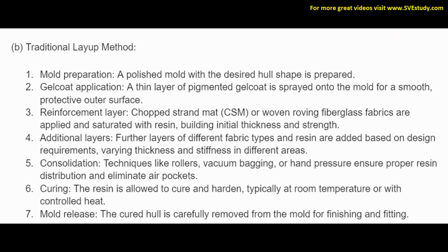B. Traditional layup method. 1. Mould preparation. A polished mould with the desired hull shape is prepared. 2. Gel coat application. A thin layer of pigmented gel coat is sprayed onto the mould for a smooth, protective outer surface. 3. Reinforcement layer.